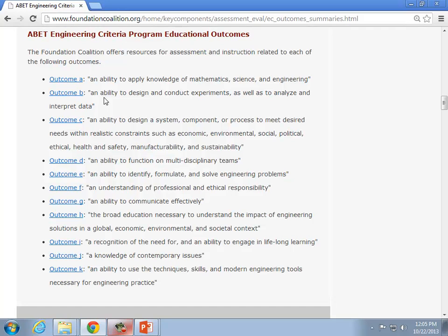In this experiment, what we're trying to find out is the C value in the Hazen-Williams equation. It's basically a coefficient that relates how rough a pipe is. When you're using the Hazen-Williams equation, a rough pipe will have a really low C value, and a very smooth, nicely made pipe would have a high C value. And so you're going to try and find out in the lab back here what is the C value of this pipe, and compare it to published C values.